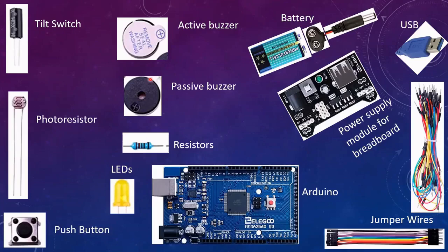There are two forms of buzzer. The one that I was showing before that has the two different sized legs, because you need to send the current in one side and out the other, is an active buzzer. That means that you just have to hook this thing up to a battery and it will buzz. The passive buzzer is a little bit different.